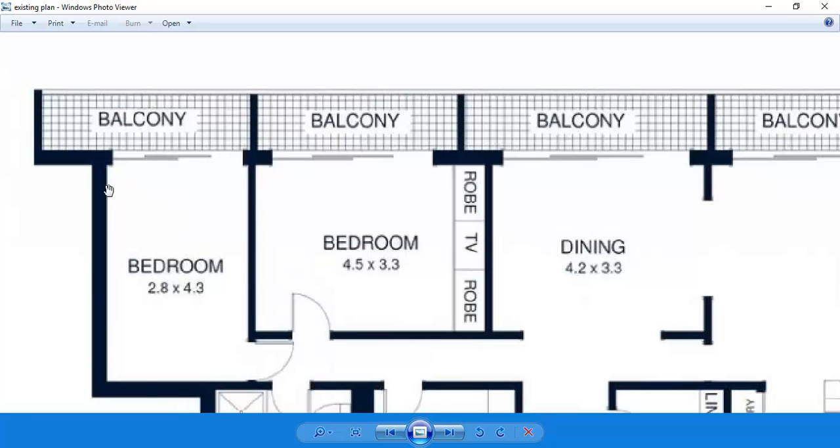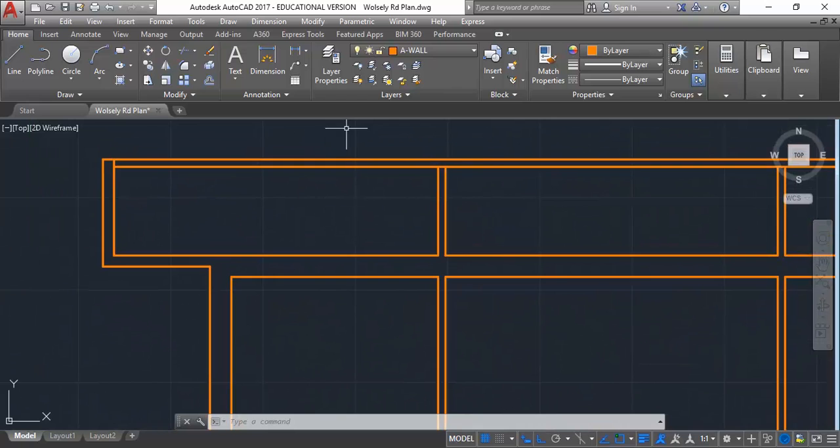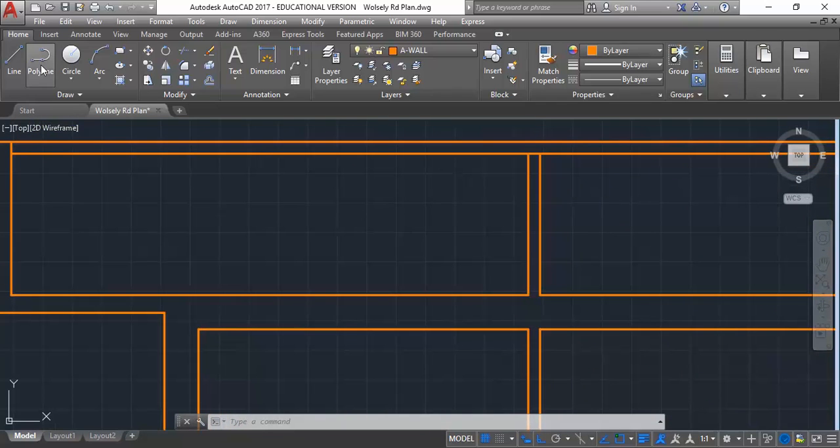So, looking at the width there, we know that's 2.8, and then we're going to have again that return, which will be at least 800, so the opening is no more than 2 metres across, and I'd say more likely it's about 1800. So I'm going to draw it that size to start with, and again, just following the same process, put in the opening first.